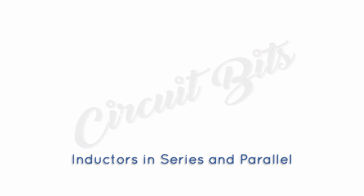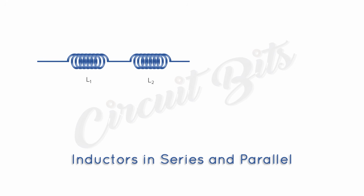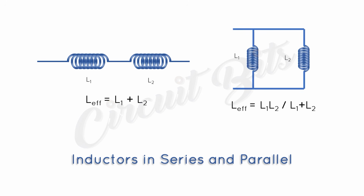Inductors can be connected in series and in parallel. If connected in series, effective inductance equals the sum of the inductances of the individual inductors, as seen in the example we have. If connected in parallel, we have L1 L2 divided by L1 plus L2 as our effective inductance.